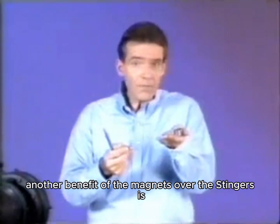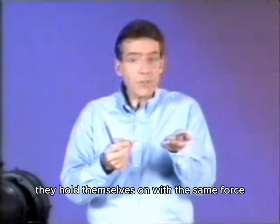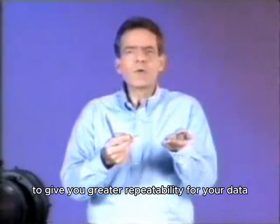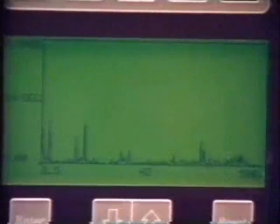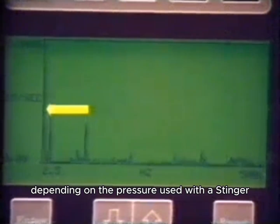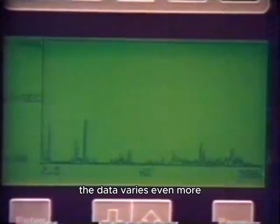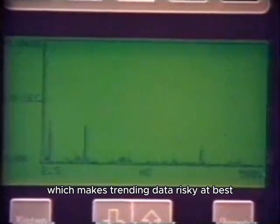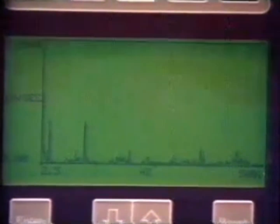Another benefit of the magnets over the Stingers is they hold themselves on with the same force time after time to give you greater repeatability for your data month after month. Studies have shown that data varies substantially depending on the pressure used with a Stinger. When data is collected by different personnel, the data varies even more, which makes trending data risky at best. For this reason, it is often difficult to get good repeatable data with handheld mountings.